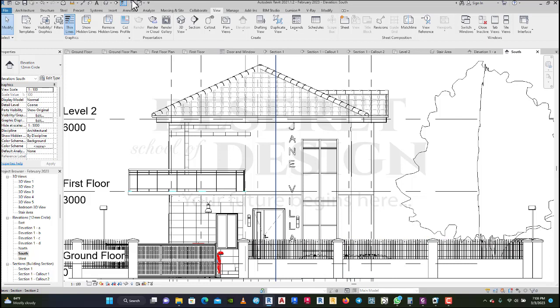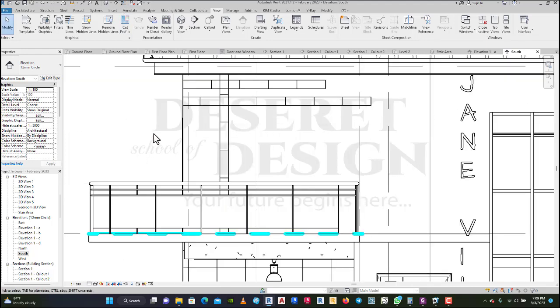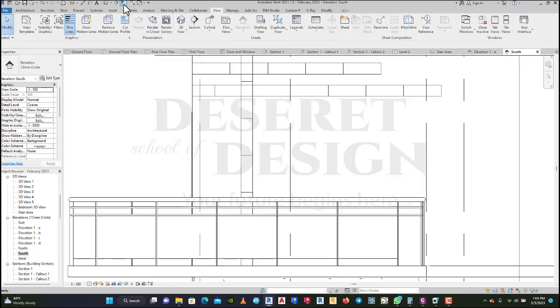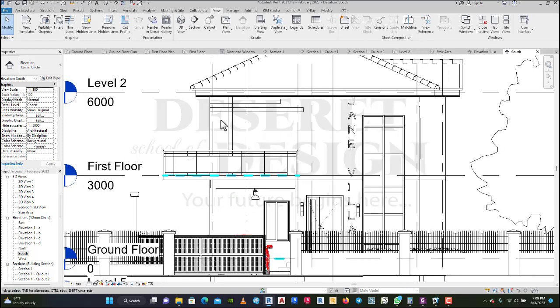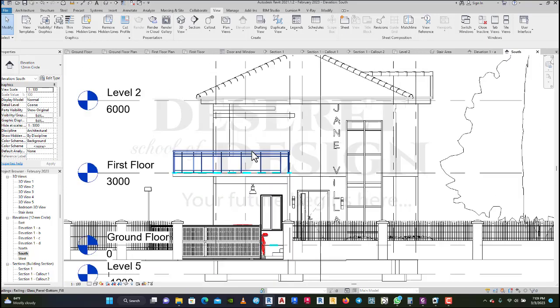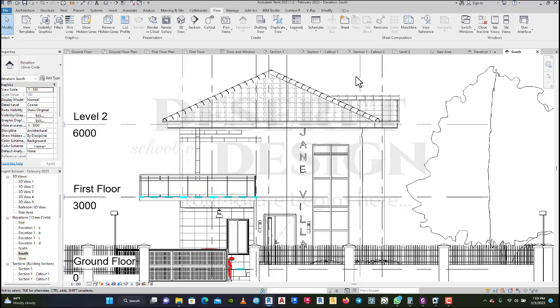So you can put the thin line on and off. Now how do you put your thin line on? This is your thin line. Now it is off. If I want the model to show every item with its line weight, you just put it on. The moment you put it on, you see what is happening. I'll put it off, then put it on. You see the actual line weight. So this is the actual line weight for most of the items. If you are going to print, before you finish your job, you want to save for PDF, you need to put your thin line on, so that every item and its line weight is on before you print out.